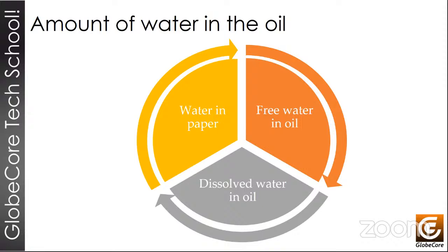So this is why it's very important to know the current moisture levels present inside the transformer in different forms, and also to take steps to correct that. It's important that during these adjustment processes, an adequate moisture measurement is made so that we can optimize any dehydration process that we run, to know that this process is in fact effective. Next slide, please.